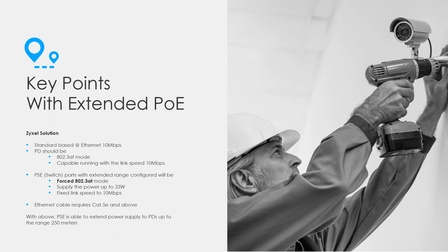Okay, so key points with extended PoE. The powered device should always be AF, so it cannot consume more than 12.95 watts of PoE power. It has to be capable of 10 megabits of link speed, either auto-negotiated or manually adjusted. And of course, it would be best if it supports the extended range PoE. Then it can automatically negotiate these factors.